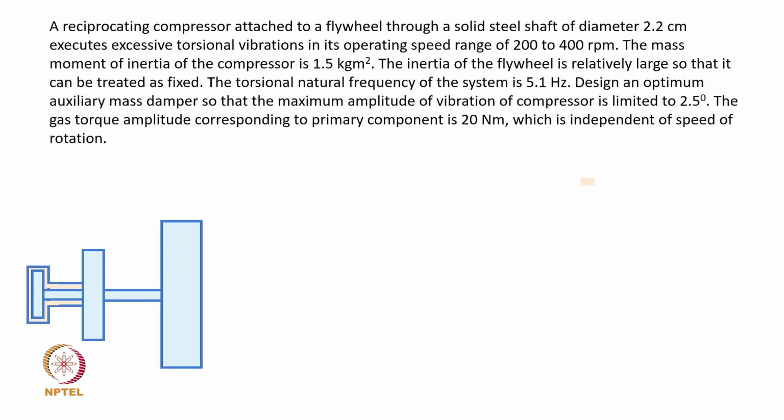It would be nice now to look into an example of a practical system, for example, the reciprocating compressor case here. This is a compressor that is being connected to a flywheel like here, through a shafting. This compressor has a solid steel shaft of given diameter and generates excessive torsional vibrations in this operating speed range.